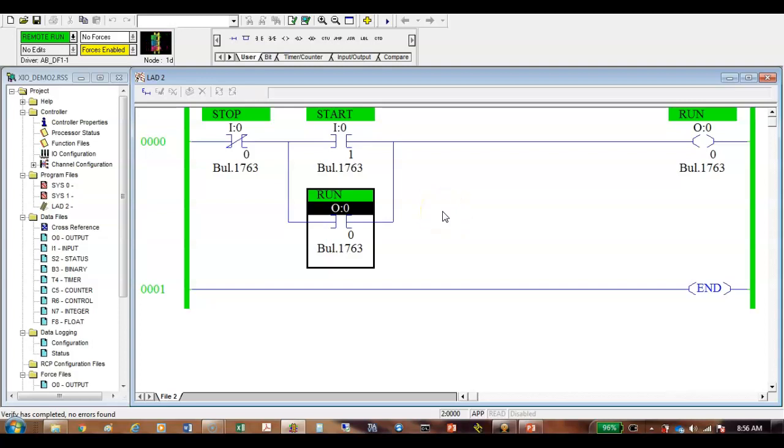So I'm using a normally closed push button. And what's the problem? It starts off false. Y'all understand? So if I open this sucker up, it goes true. So that means I would be using a normally open push button for a stop button. Now what's wrong with that?